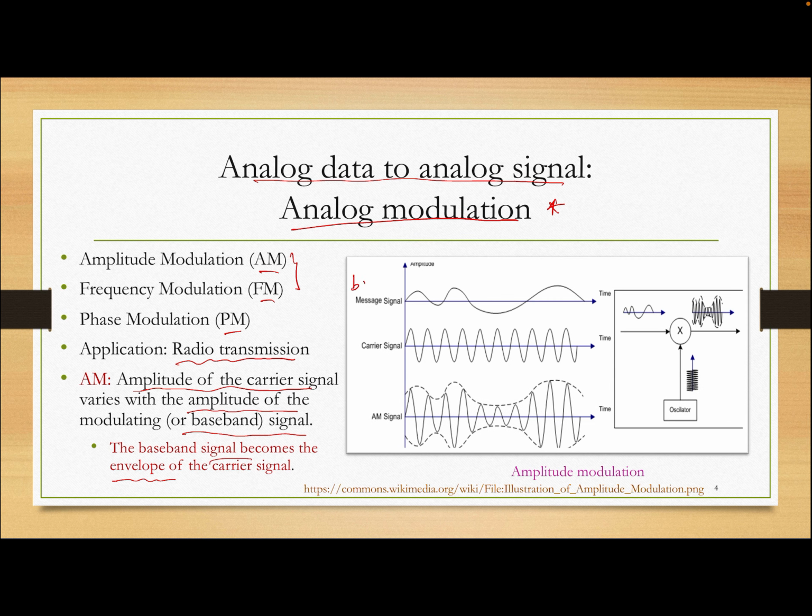This is my baseband signal, the low frequency signal, in time domain. And this is my carrier. My carrier is a sinusoid signal, sine omega ct or cosine omega ct. This one I use sine over here because it starts with 0 phase. Then this is my AM signal after I modulate. You can see that the amplitude of the carrier varies based on the amplitude of the modulating signal. So this envelope looks like this.